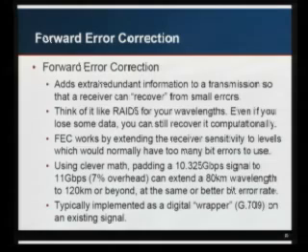And the way that it works is it extends the receiver sensitivity. So where you might have a receiver that was losing one out of 1,000 packets, 10 to the -3 or -4 worth of signal, that would be completely unacceptable. Because of this, it's now able to recover almost all of those, and it takes your bit error rate down to something acceptable. And so you can get much longer distances out of it. There have been a couple of different algorithms out there, but basically you're using clever math, and you may pad the signal by 7%, and it may give you a pretty significant distance increase and a lower bit error rate at the same time.